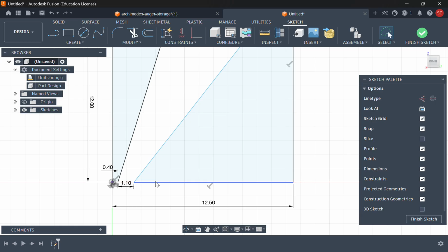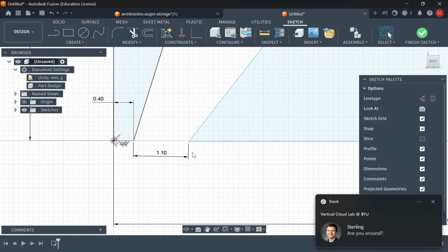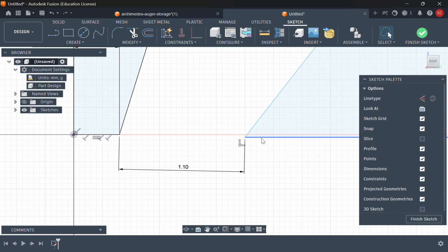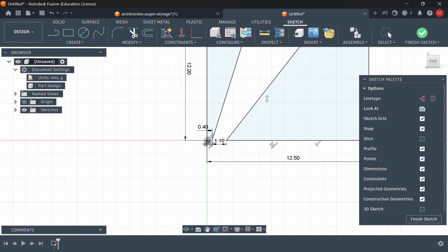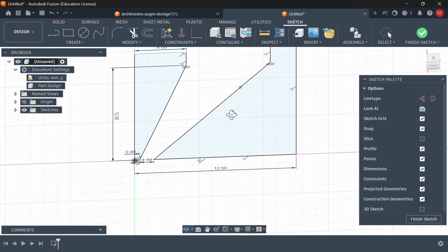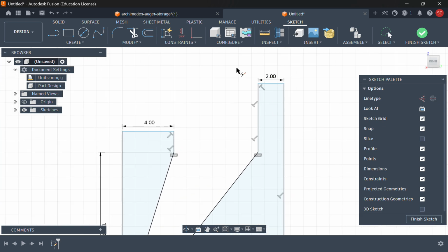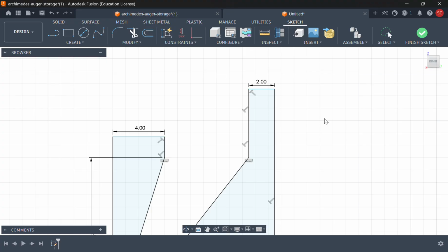Okay, so down here, if you can see, if we zoom in, having some problems down here. So this is getting off. These are not actually aligned. So what I'm going to do here is I'm going to select these 2 lines and make them collinear. There we go. So now it's perfectly on that line. That is great. Most of these things down here are black lines, which means that they're all defined. That's perfect. Then we just need the vertical heights of these.